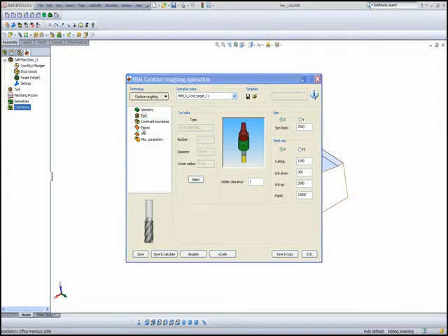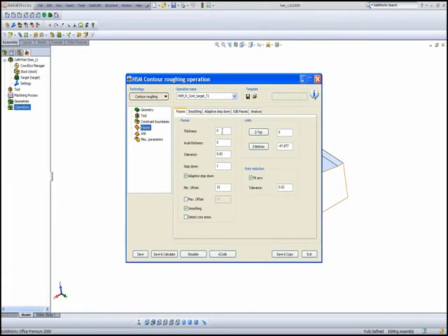Let's go now to our passes. In our passes, we will leave a thickness offset to the tool of 0.5. You'll note that when I put the value of 0.5 here and I go to the next field, the 0.5 is automatically added to my axial thickness, to the bottom of the tool. Since I'm doing a rough cut, I'm going to have my step down every 3 millimeters. And note every single field that I go into, by the way, note the pictures on the left hand side describing what each field does.